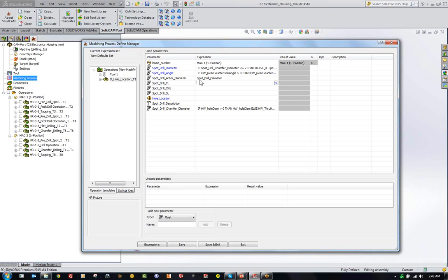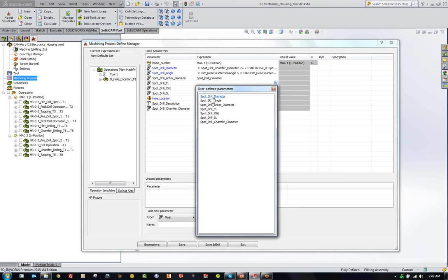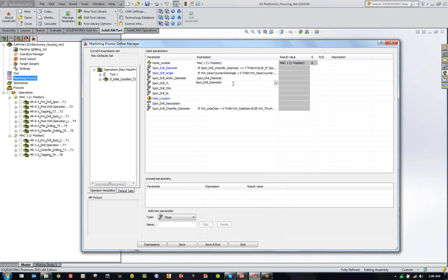What about the tool length? Okay. This is where you have to start making some decisions. Do you want to hard code this? Do you want to use ratios? What I did is I went in and I looked at the machinist handbook for jobber length drills, and it says in general they're about 14 times the diameter of the tool. So what we did in here was we decided, all right, we'll just make this a user-defined diameter times 14. And we're going to capture that.